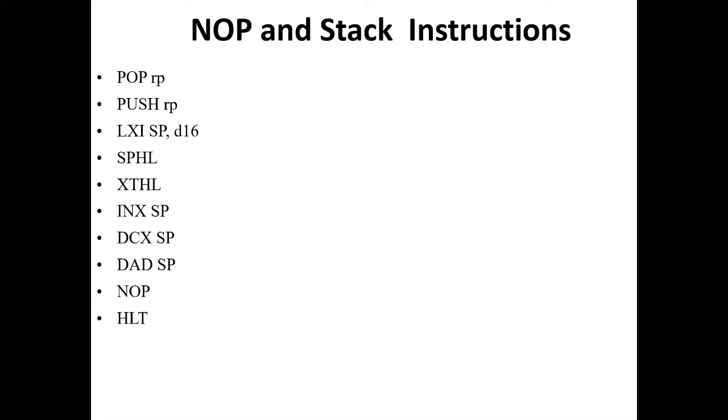So after executing this instruction, SP becomes FE08H, accumulator becomes 55H, and flags become 66H.